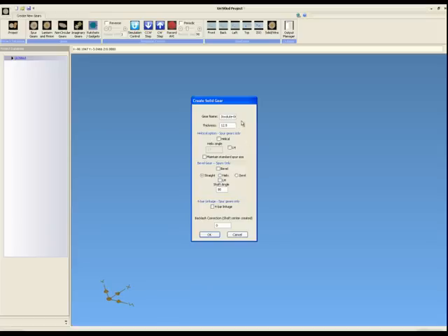When we do this, the top box is gear name. You can enter any name you wish for the gear. However, the program, in order not to have gears of the same name, will automatically fill in this box with involute or helical or bevel as the name of the gear, and follow that up with a suffix of the number of the gear. If it's the 14th gear you've created, for example, it could come up and say bevel number 14. The database is organized by the gear name, so it will not allow you to name two gears the same.